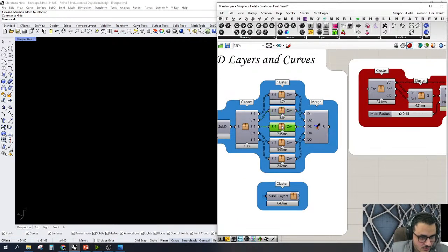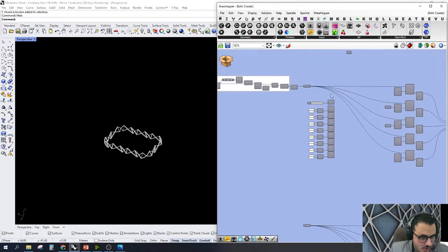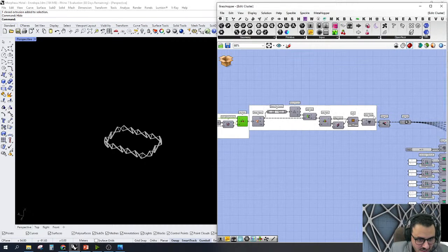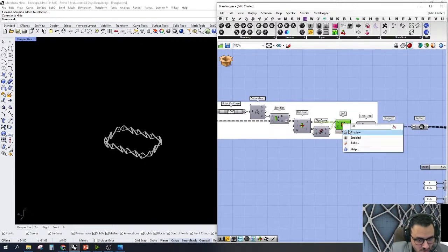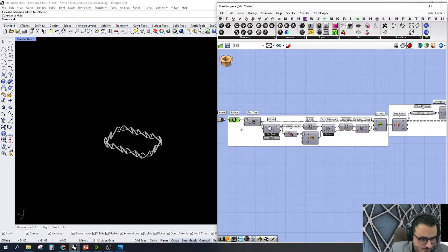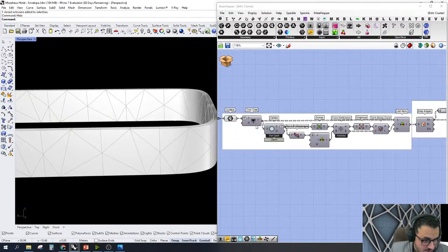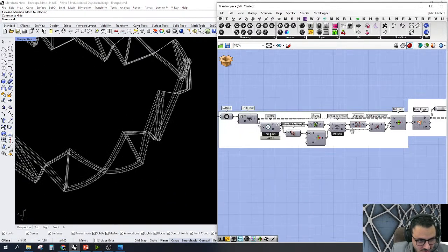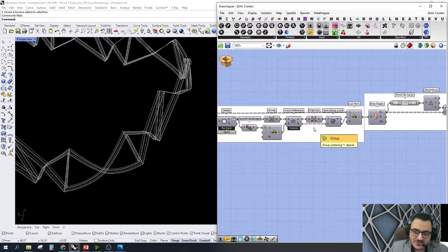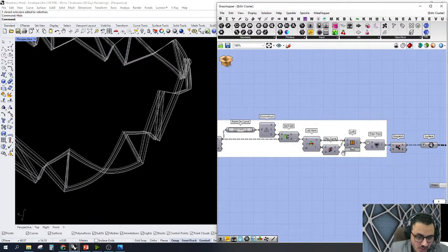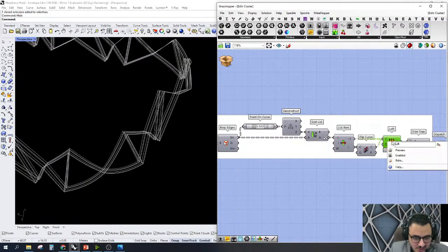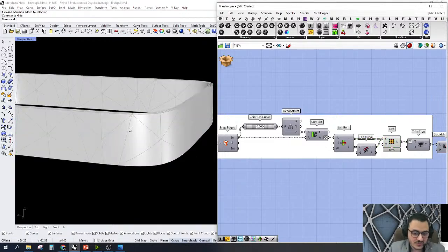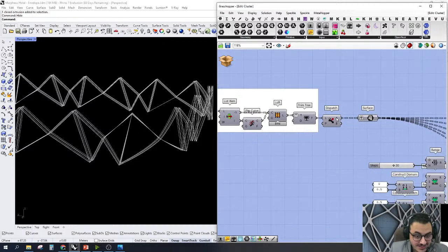Okay, let me show you what's happening in here. In this case, again, I sorted the curves. I sorted the surfaces. They are already lofted, or maybe ruled surfaces. They are simple. At least two curves are linear. So I sorted the curves, I made ruled or lofted surfaces again, and I dispatched them.